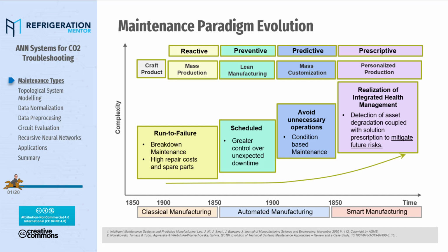The last approach is focused on seeing the system in a prescriptive way, in which every failure has a solution, and the same failure can degrade another part of the system or the whole system as well. Similar to a doctor approaching as an internist, seeing the system in a holistic way in which all parts work as one. This is because the refrigeration system has a high dependence between variables. It is impossible to have relevant results analyzing only the pressure or the temperature or the current.